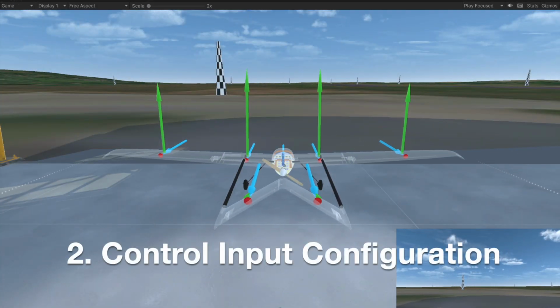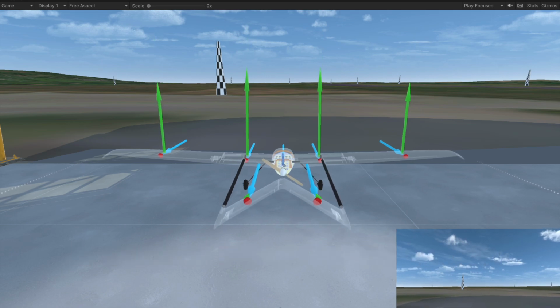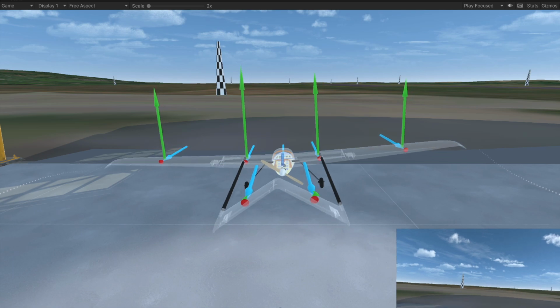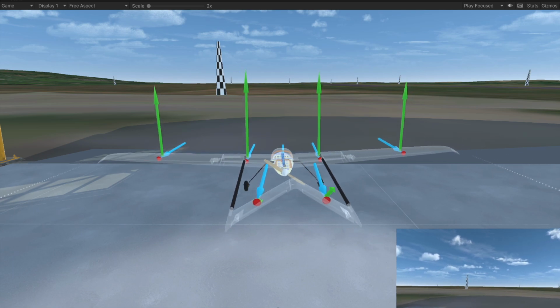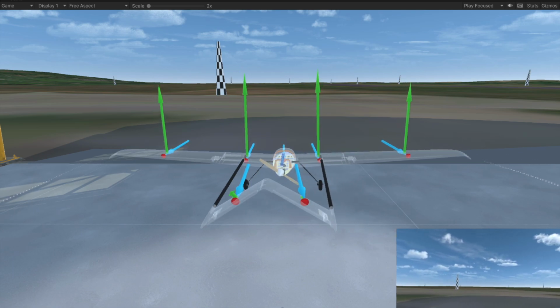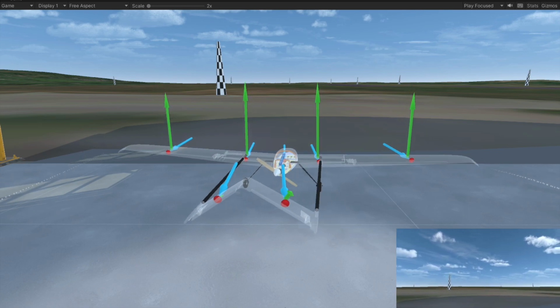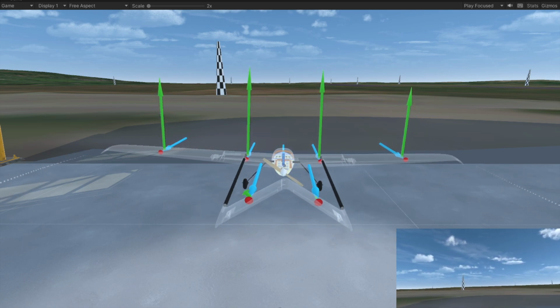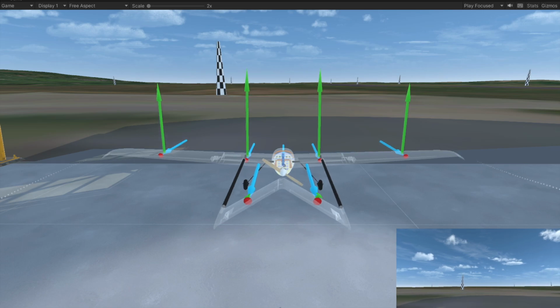We will now check the flight controls and assess the input and output for the required aircraft motion. The elevator controls in this aircraft need to be reversed. The ailerons also need to be reversed to provide a roll right and roll left response. The rudder should provide a yawing motion in the left and right directions.